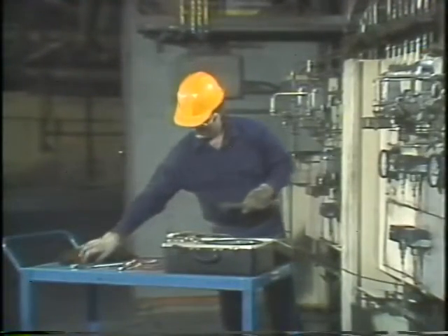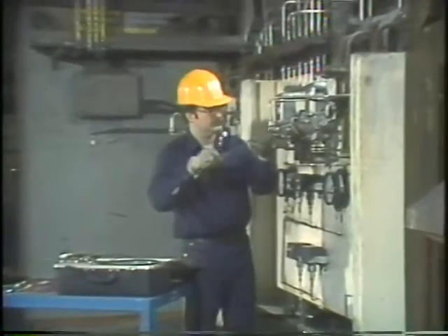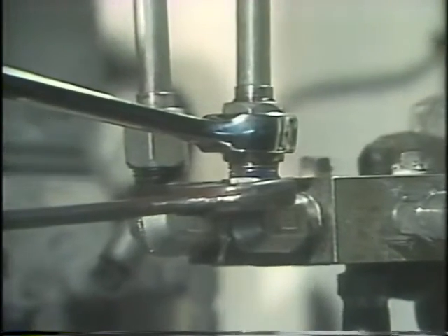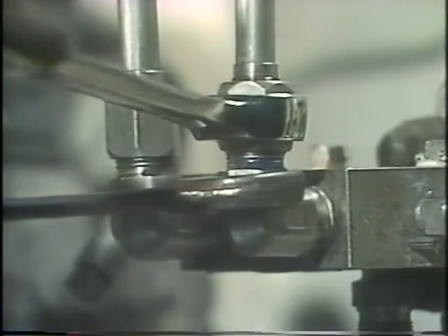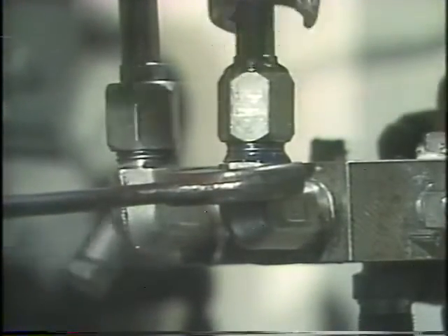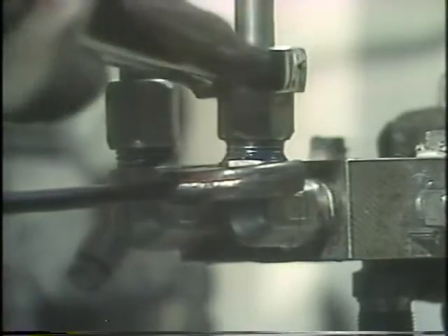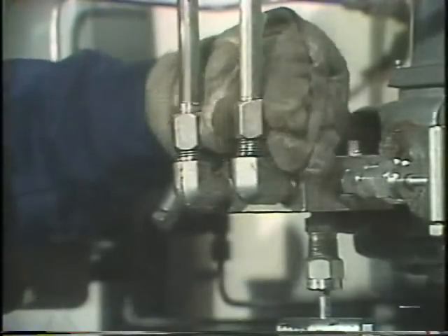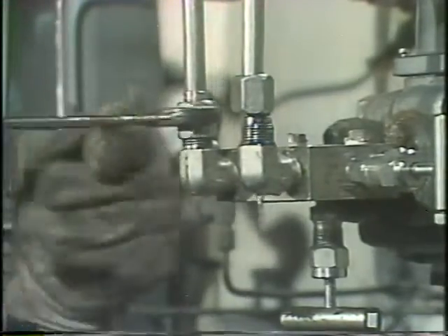Now I'll disconnect the process piping that goes to the transmitter. To do this, I'll need a backup wrench and a tubing wrench to prevent damaging the tubing coupling. I'll do this slowly so that I can bleed off any pressure trapped in the line. A couple more turns ought to take care of it. Now the same for the low side. Screw these nuts off and I can move the tubing out of the way. Now I'll take care of the low side tubing.